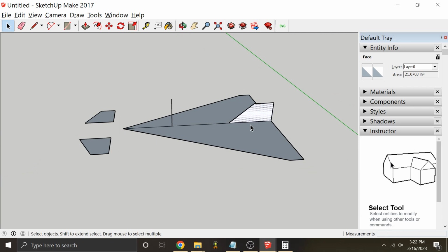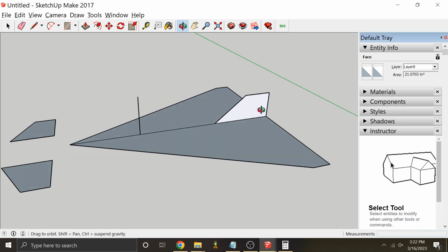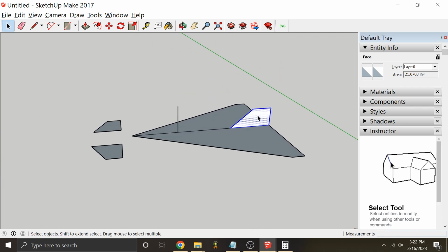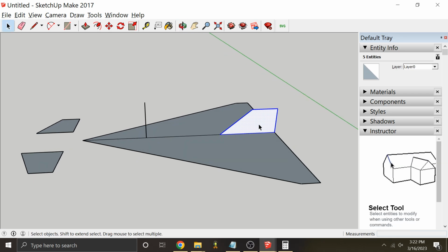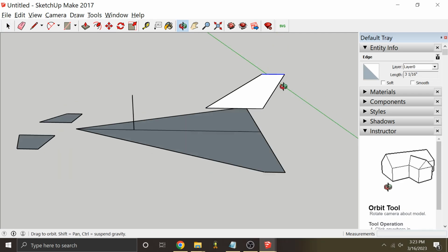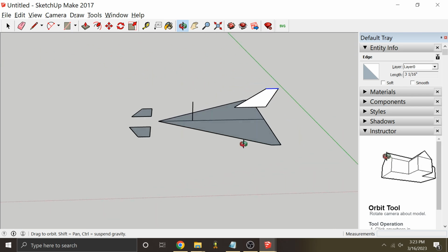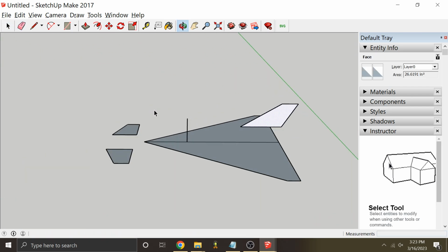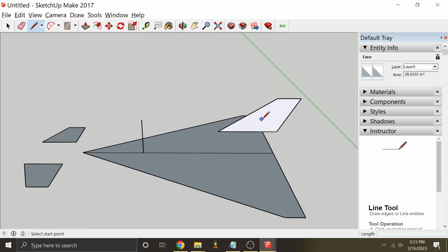That's actually bigger. And I'm thinking about it, this looks fairly small. I think we're going to go probably a lot larger on the vertical tail here. So something around that seems reasonable in terms of sizing. So then the quarter chord of this is probably going to be somewhere around here, and that's going to be about 16 inches.